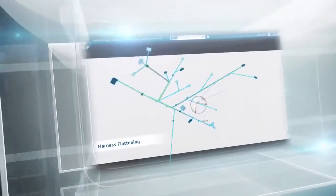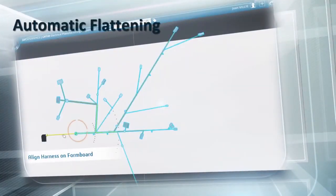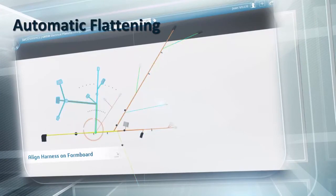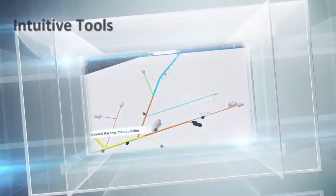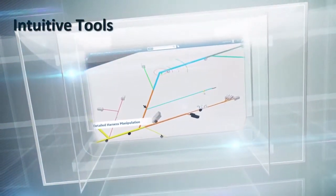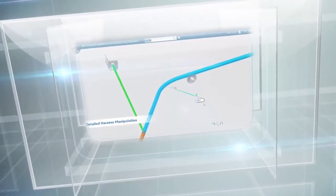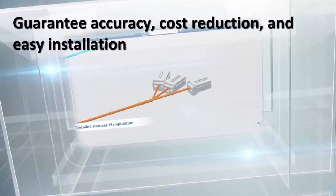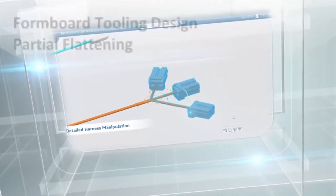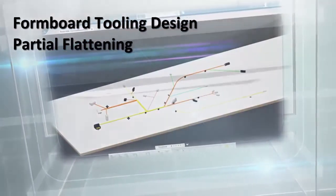Thank you, Dimitri. To summarize some of the key capabilities for Formboard layout design, first, you may have noticed automatic flattening of the 3D electrical harness, a simple click to flatten the entire 3D wire harness. Next, on the 3DEXPERIENCE platform, we have very intuitive and easy to use 2D harness layout tools to manipulate the bundle segment. The combination of harness design in context plus harness flattening guarantee accuracy, cost reduction, and easy installation of the final product. Some of the additional functionality is Formboard tooling design and partial flattening for complex rigid harnesses.